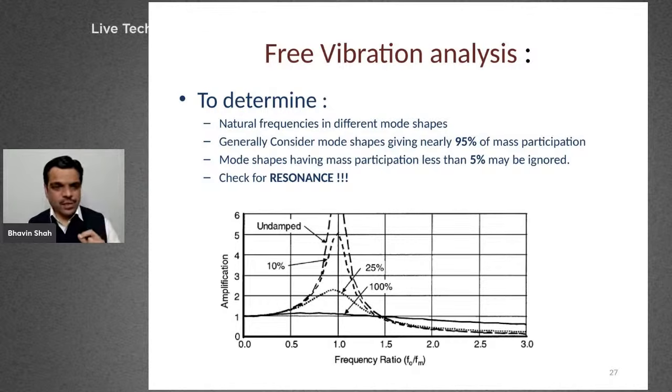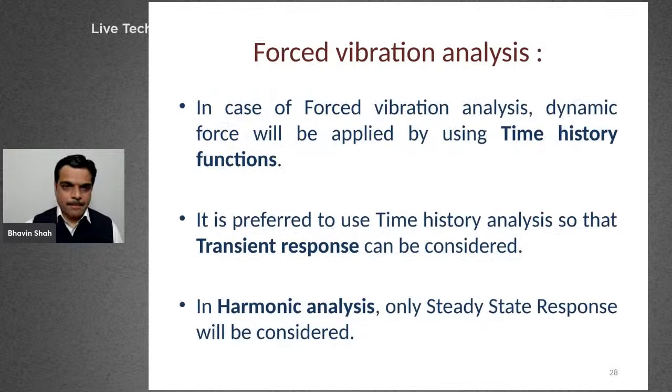And there were a few incidents in which a number of iterations happened to remove even those higher modes, because it was almost matching, and that was creating problems in terms of amplitude. Okay. So these are the kind of information which we'll get out of free vibration analysis. So after performing free vibration analysis, we will perform forced vibration analysis. In case of forced vibration analysis, the dynamic force will be applied using time history functions.